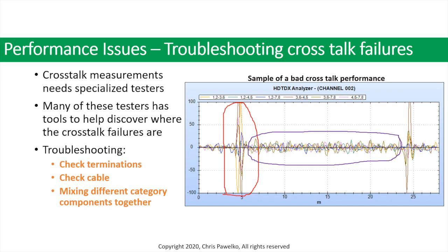And then last but not least, if we look at the far end connector, we do see some issues happening here. So with regards to this particular type of test, we could turn around and look at the different colors and say, hey, you know what? The terminations on 3, 6, 7, and 8 are the issues. But in all honesty, you would want to go back in and re-terminate that connector.